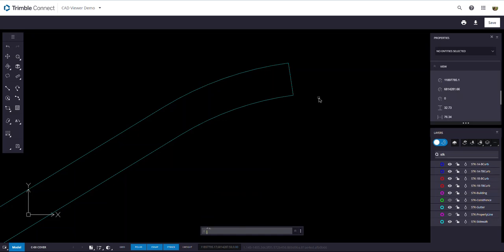So let's do a polyline edit. Let's pick this line, and you can see that it's not a polyline, so we're going to turn it into one. We're going to say yes, and then we can go ahead and say J for join, and let's try it that way. Still not joining it. So not sure why, but what we can do is set this layer current.